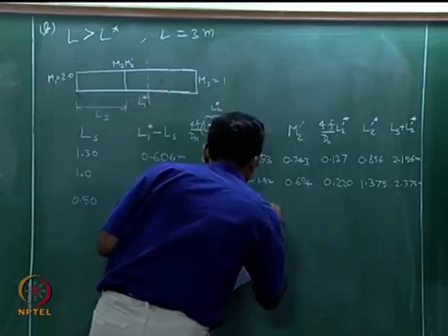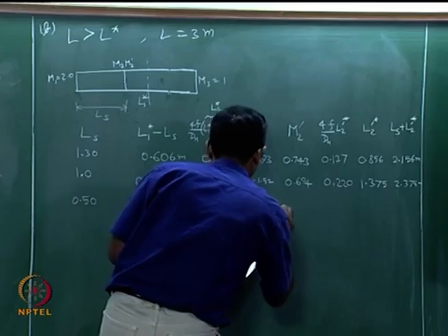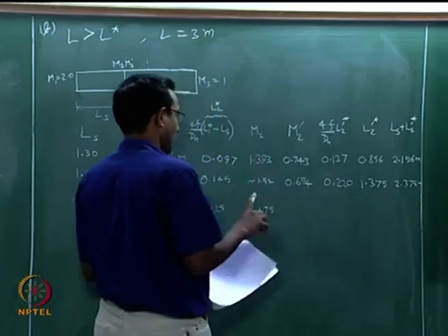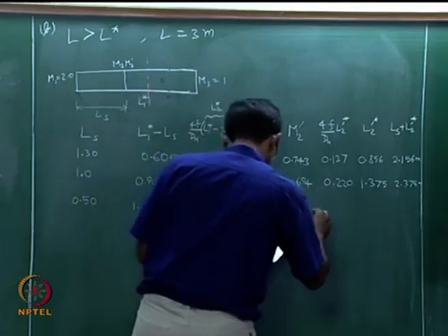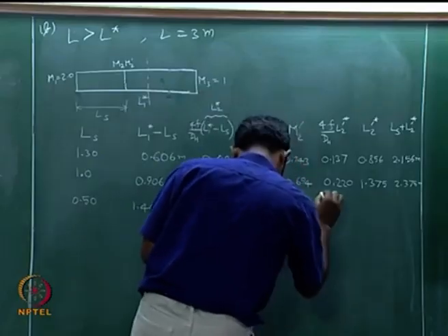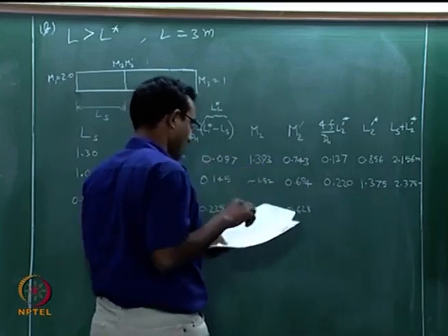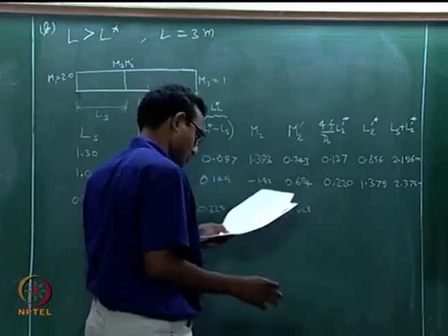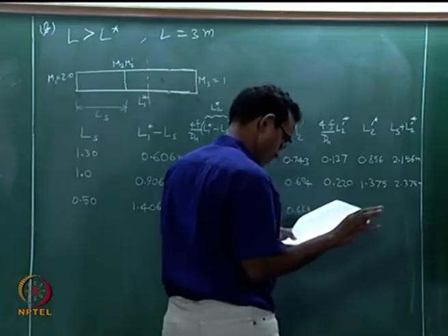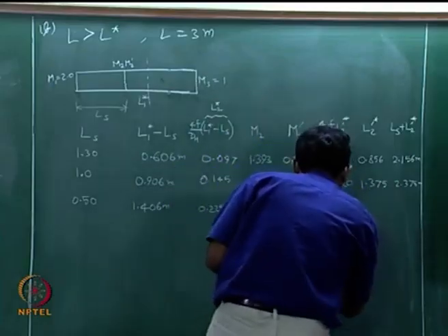M2 is approximately 1.75 Mach number. From there, normal shock tables give me 0.628 Mach number downstream of the shock. From here I go back to Fanno flow subsonic solution, gamma equal to 1.4, I am going to get 0.391.